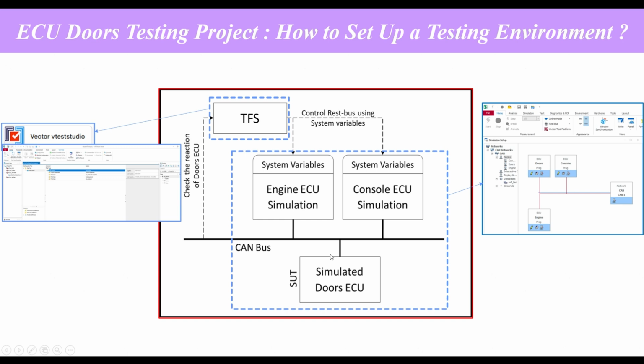Then we also simulate the console ECU in CANoe, which represents commands coming from the vehicle interface, for example, a door lock or unlock request triggered by the driver.